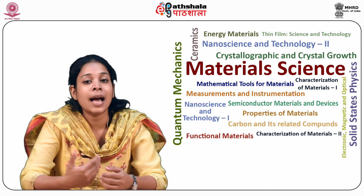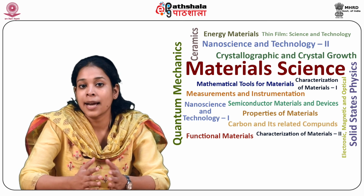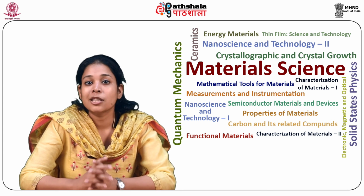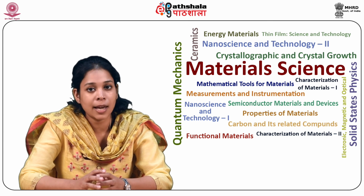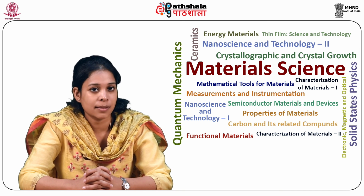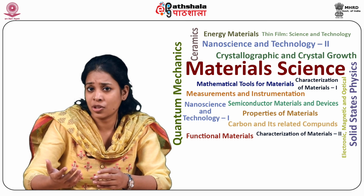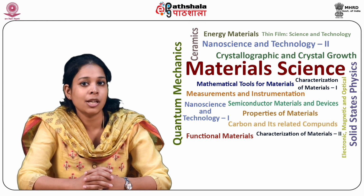The mixed covalent and ionic bonding we have also read in this module, and these two bondings result in very high hardness, that is 9 on the Mohs scale, and a very high melting point, which is 2050 degrees Celsius. The strong atomic bonding and hexagonal structure make the dislocation motion very difficult in alumina, and some basal slip on the basal slip system occurs above 900 degrees Celsius. Most of the alumina ceramics have siliceous phases at the grain boundaries, which flow and cause the deformation at temperatures varying from 800 degrees Celsius to more than 1100 degrees Celsius depending on the purity of the alumina.